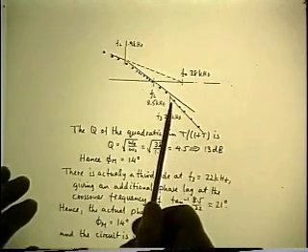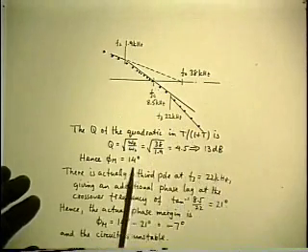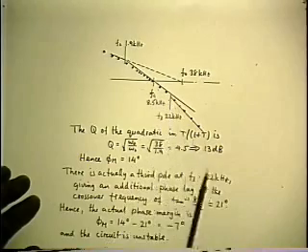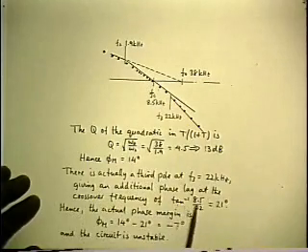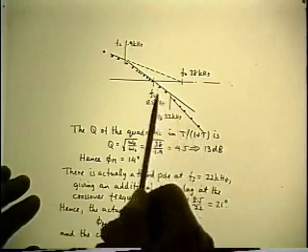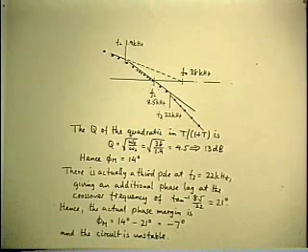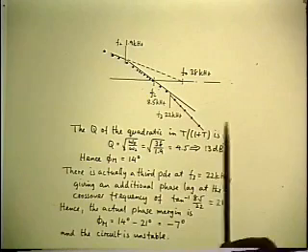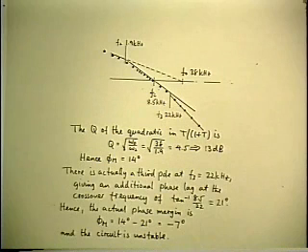Now, does that confirm that it should have been unstable? Yes, it does, because the original phase margin was 14 degrees. But the third pole is going to contribute an additional phase lag at the crossover frequency of arctangent 8.5 divided by 22, which is 21 degrees of phase lag, so the phase margin becomes -7. Therefore, it's unstable. So the benefit we have from all this is that we've identified what the mistake was. Now you have to track that back and see why it happened.